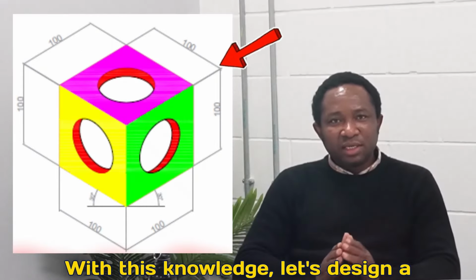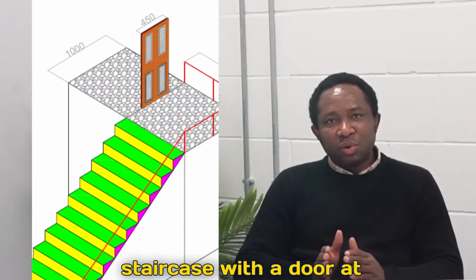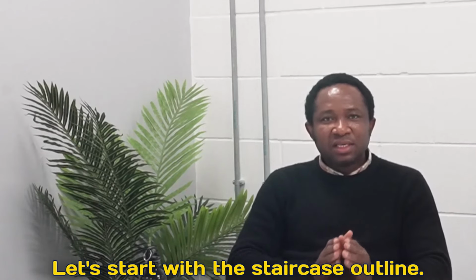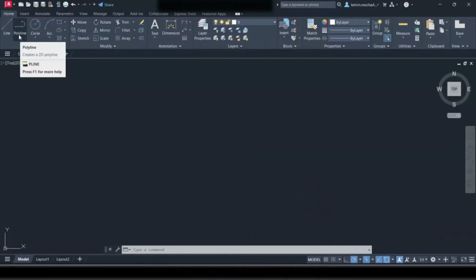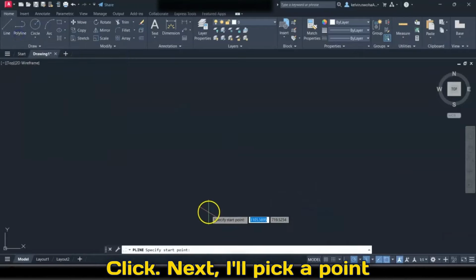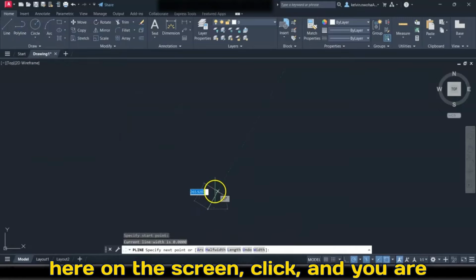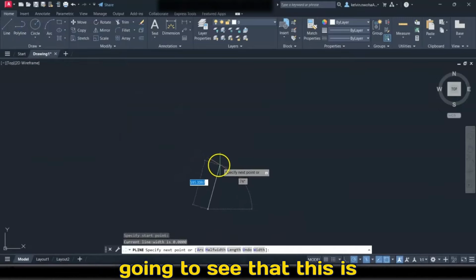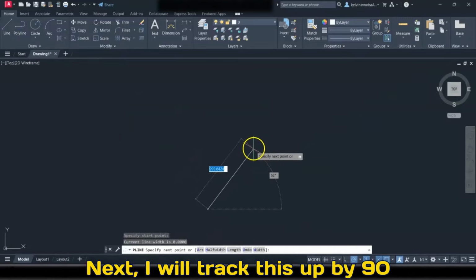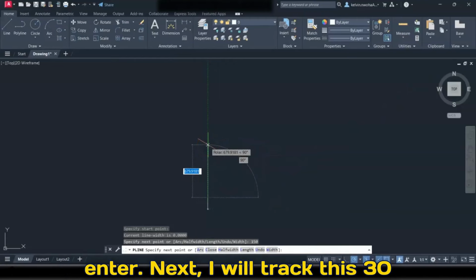With this knowledge, let's design a staircase with a door at the top floor. Let's start with the staircase outline. Next, I will click the polyline tool. Click. Next, I will pick a point here on the screen. Click, and you are going to see that this is tracking. Next, I will track this up by 90 degrees. I will type 150. I will press enter.